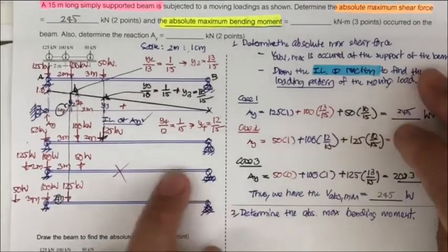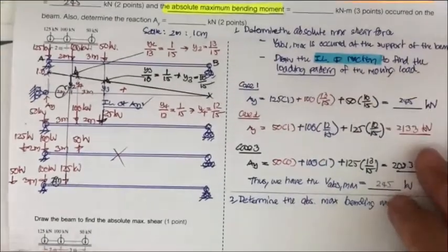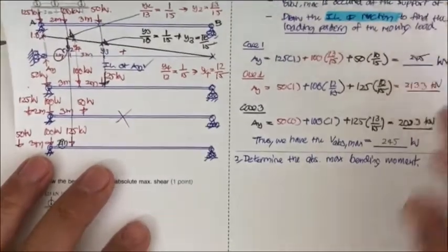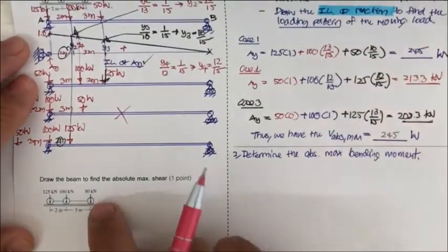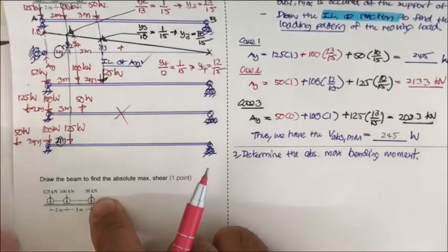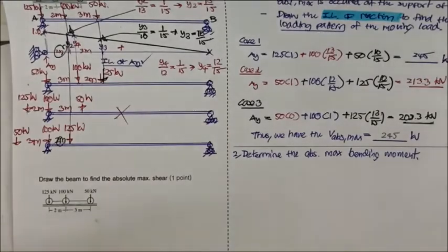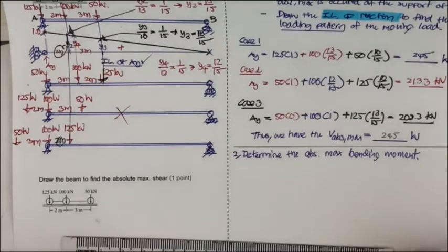By doing this, we have a set of moving loads, and we will have steps. The first one, determine the resultant of this load. The second one, you may determine the position of that resultant force with respect to a reference line.